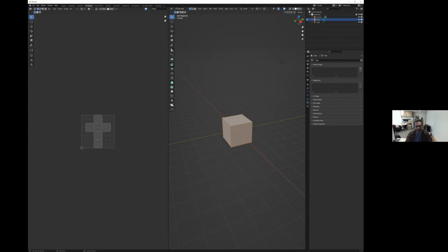Typically a texture is nothing more than a two-dimensional matrix of pixels. And to apply a texture correctly to a 3D object, you must tell it how to map those pixels from a 2D space using X and Y to a 3D object that uses X, Y, and Z. Doing that conversion is called UV mapping. Given the time and what we were trying to cover in this class, we will revisit this in future workshops. For now, we will only use procedural textures to style and design.